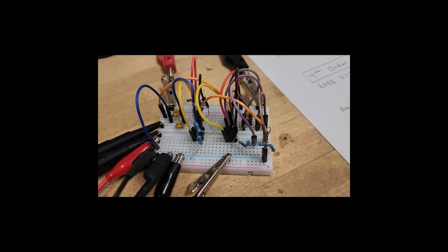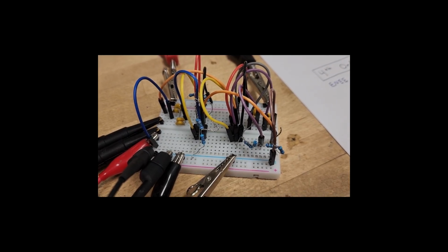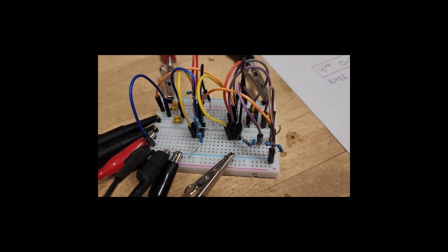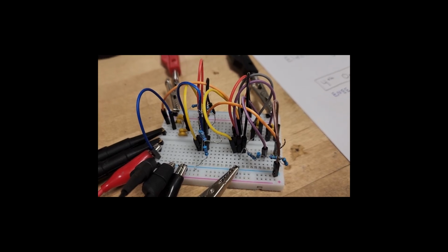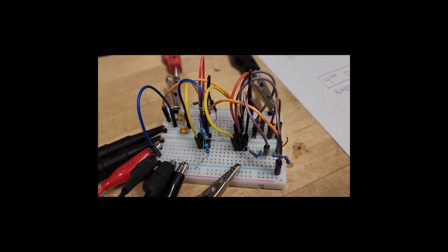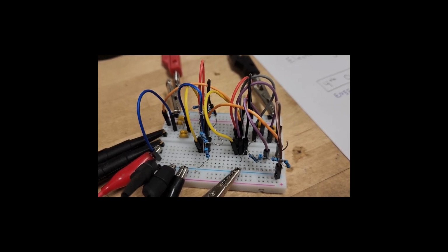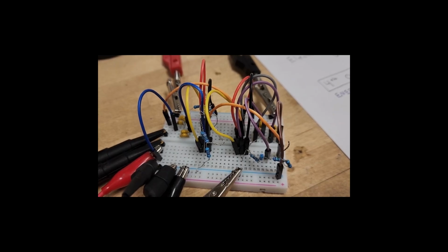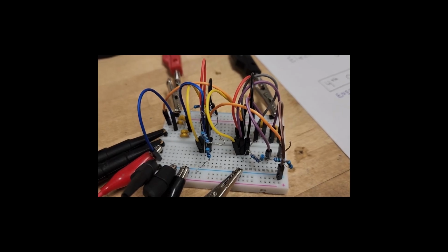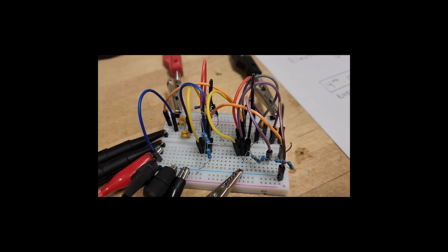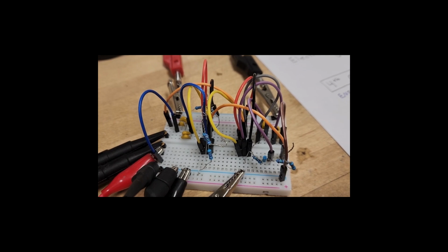Also, during the construction of this circuit, due to the fact that we are building it on a breadboard with all these wires and not soldering the circuit, there is a lot of noise that has been introduced into the circuit. Therefore, by increasing the amplitude of our input signal, we are able to avoid the noise artifacts as much in our diagnostic of our circuit.